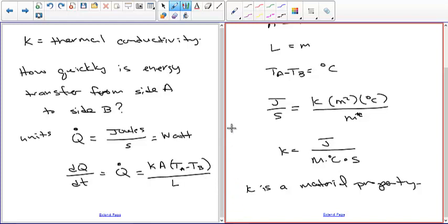That's the general rule with computers: you want to be as far away from thermal equilibrium as possible. You want to keep a huge difference between your component and the air, because the closer it gets, the slower the heat transfer. But you don't want it too hot or you're going to burn it, so as long as you don't damage the thing. The bigger the temperature difference between the component and the air, the more heat transfer rate you have.